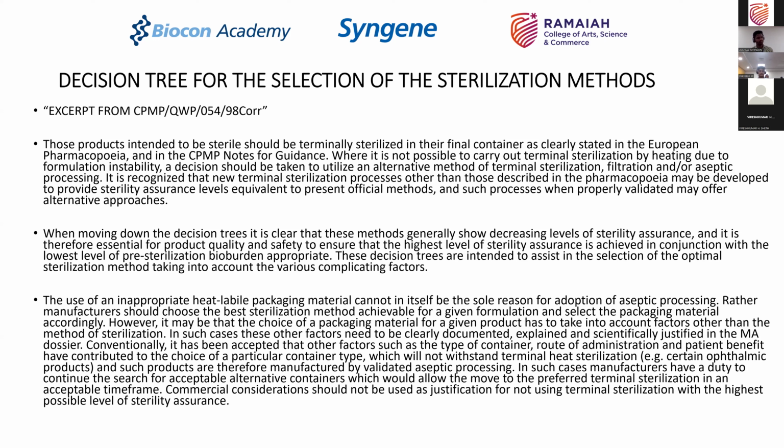Those products intended to be sterile should be terminally sterilized in their final container, as clearly stated in the European Pharmacopoeia and in the CPMP notes for guidance. Where it is not possible to carry out terminal sterilization by heating due to formulation instability, a decision should be taken to utilize an alternative method of terminal sterilization, filtration, and or aseptic processing.